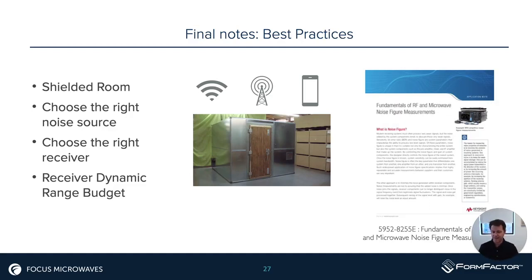You can't just mix and match anything and hope to have a measurement from 2 to 110 gigahertz in a smooth curve. You might have to divide that band up. You might have to choose the right attenuation. So there's a lot that goes into it before you actually do the measurement. Because I see this a lot of the time: oh, we see a saturated curve, what's wrong, the system's not working? But in the end, we just need to do a bit more analysis ahead of time to make sure that we budgeted the dynamic range correctly.